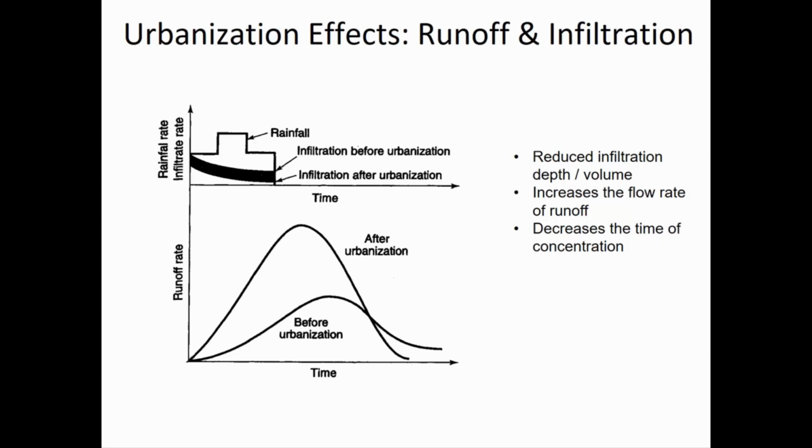All of the water underneath this top line, before urbanization, all of that water infiltrated. And I'm going to write a conceptual formula on the whiteboard here: rainfall excess equals rainfall minus infiltration. Another word for rainfall excess is runoff.